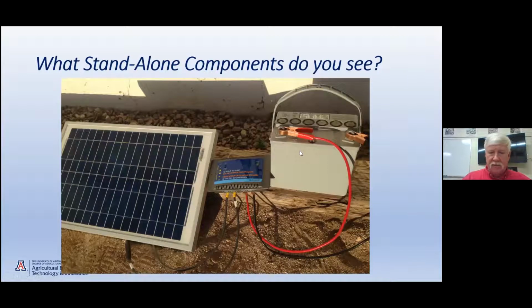All right, so the charge controller, and I'll tell my students, it's like my wife when I go to a buffet. My wife is the one that says, Ed, you've had enough to eat. Stop. Okay, so she's my charge controller. Otherwise, I'll just keep eating and eating, and I'll feel the effects afterwards. So the charge controller here, again, serves to monitor how much energy is going into the battery, the state of charge of the battery when it's full. And so when the battery is full, it'll automatically disconnect the solar PV module, so it's not damaging it.